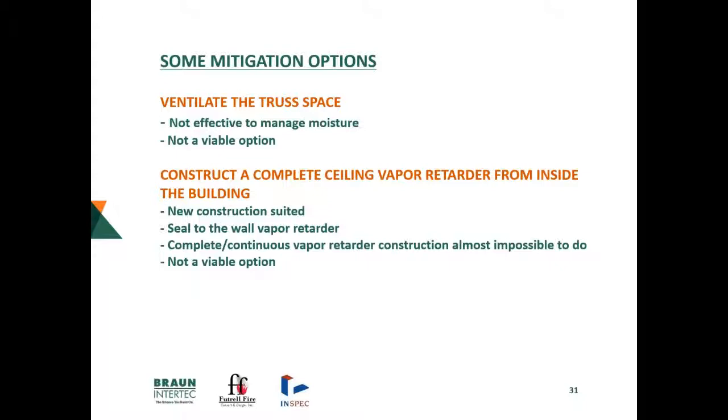Constructing a complete vapor retarder from the inside really would be great. That's what we intended on doing with this whole business of poly vapor retarders in the ceiling, but it's just very, very difficult to do. We have seen cases upon cases where you just can't get that vapor retarder installed continuously, it's incomplete. And at this point, we're really not seeing that as a great option.